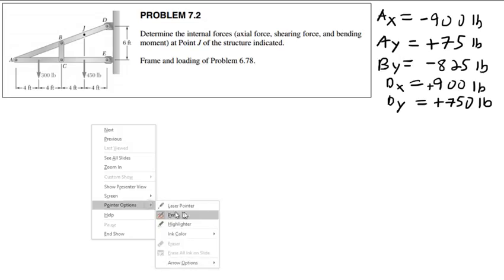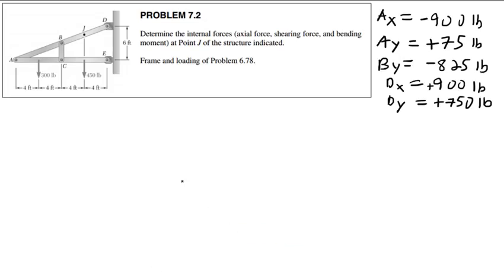Okay, so what I want to do next is translate these into forces. In order to do this, member forces are always determined along the local axis of the member. Member forces are always determined along the local axis of the member. Okay? So let me show you what I mean by that. When we talk about members, we're talking about shear, moment, and axial force. But these are forces along the member's own axis, like an x prime axis.